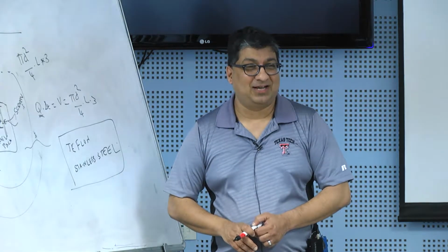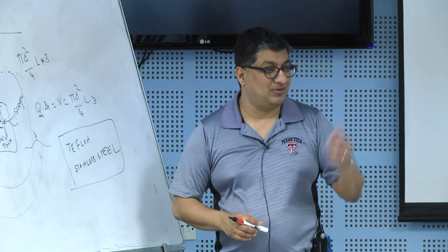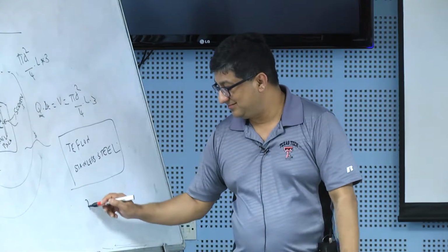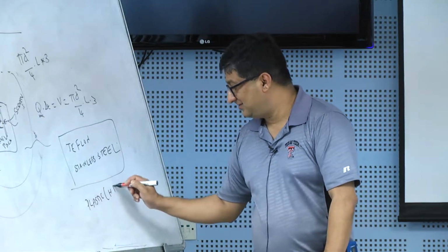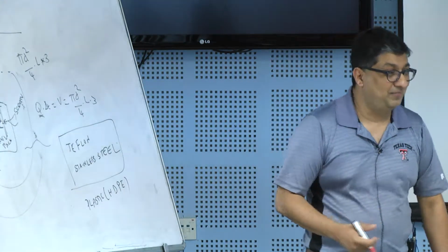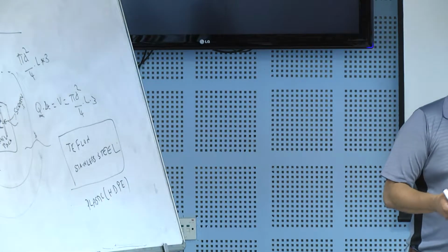You don't want to put glass because glass is silica. So some of the metals may actually sorb onto silica. Or high density polyethylene. And then if that chemical is reactive to sun, we want to collect it in dark colored bottles as opposed to white bottles. So those are called amber colored bottles.